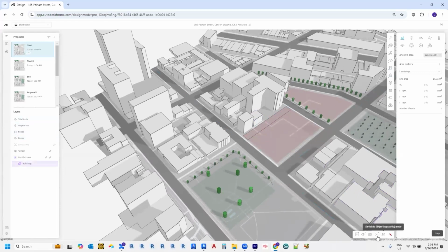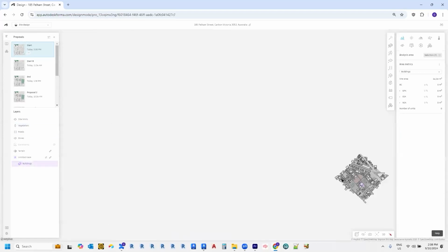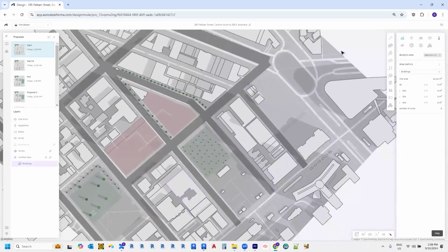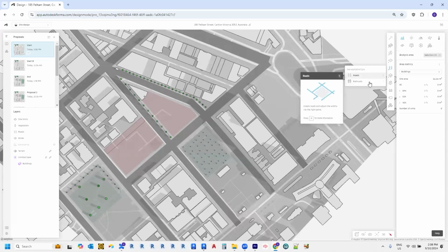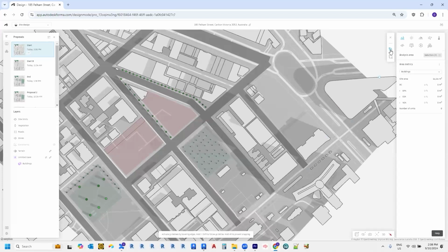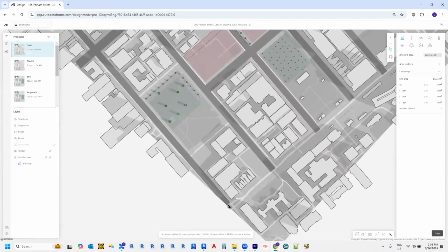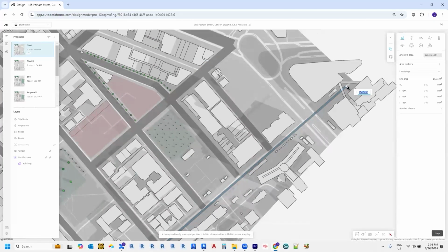Now, moving on, the next major site modeling tool we've got is to add roads. In order to add a road, you click on the transportation tab here and click on road. You can also add railroads if you need those. But typically you'll want to be adding a lot of roads. So I've just clicked on the road function, and similarly, we just click a start point and an end point. And we'll just end it there.